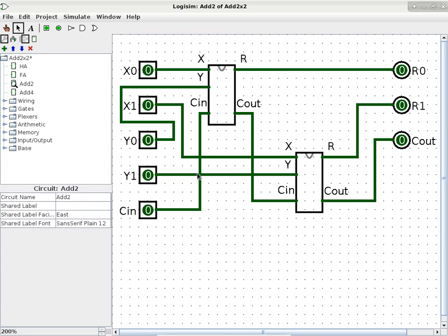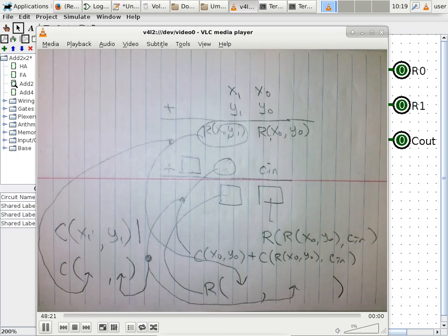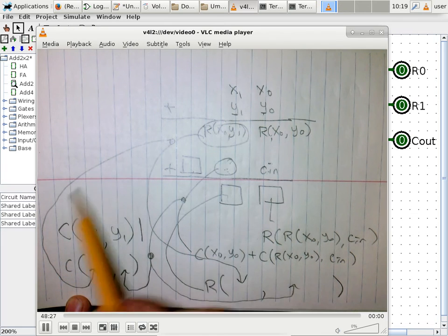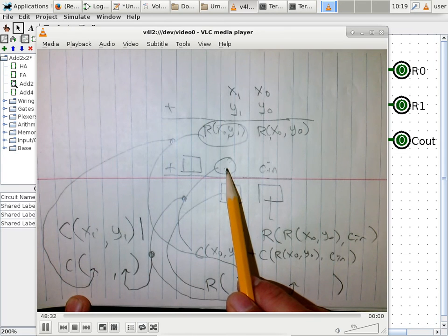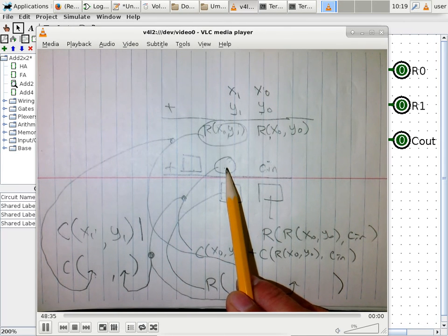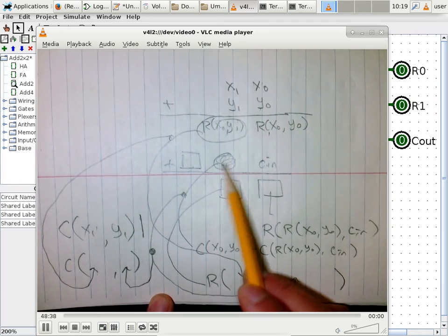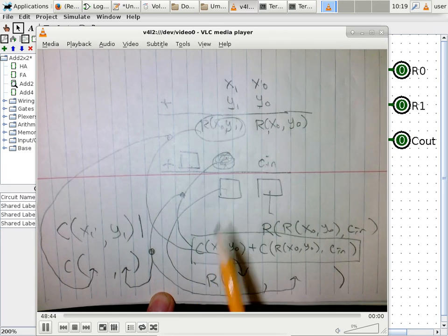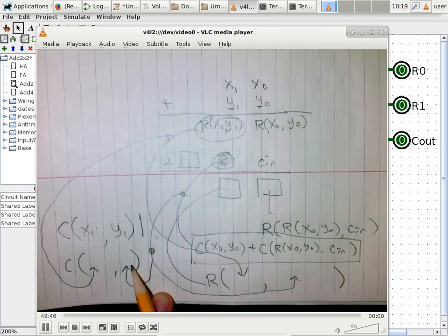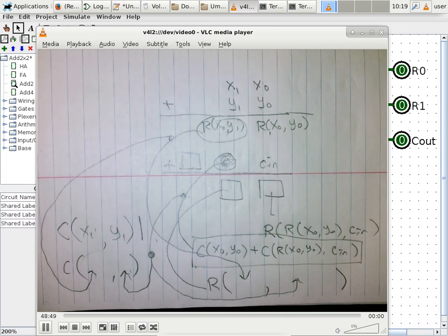When you look at the document camera, it looks simple because this traces back to this whole thing here, which is not too complex. But anything that relies on this one here, which is the carry bit of bit 1, is complex because this bit by itself is actually like this big already, right? And yet it feeds into the carry of this bit here. So you can kind of imagine how ugly it can look when you work on bit, okay, I don't even have to go too far, bit 15 is going to be really ugly already. Bit 3 is far enough.